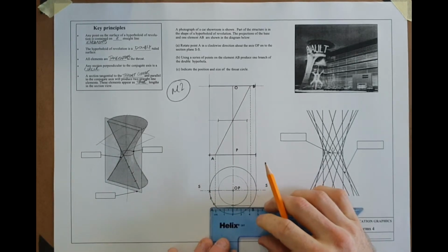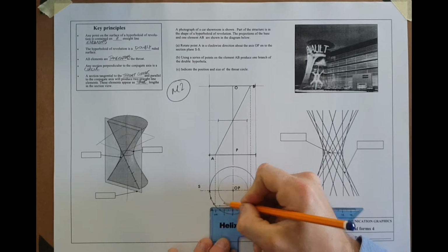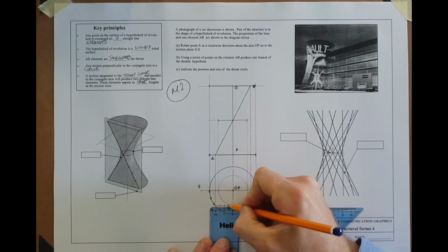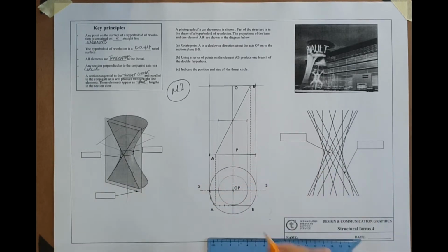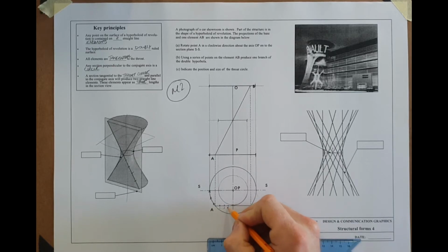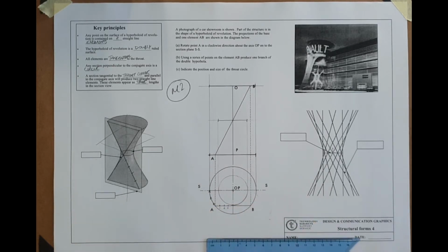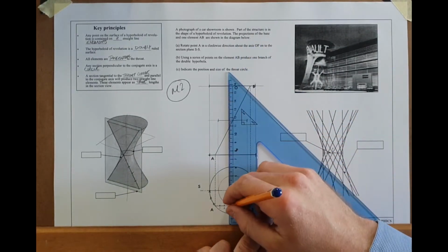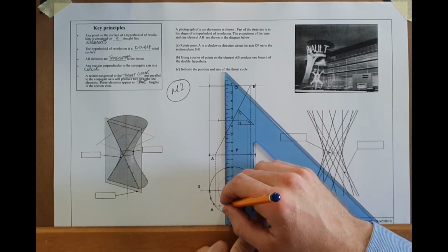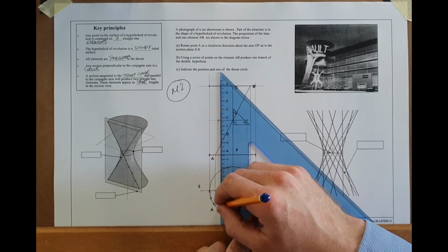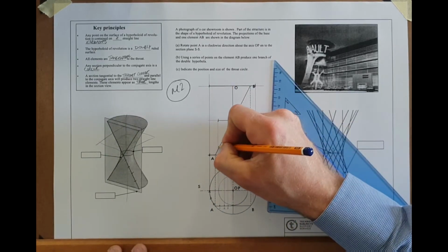So I'm going to lay them down here in plan. In plan it's approximately 20. I'm going to go 5, 10 and 15 there. 3 points will do. Okay, I'll call them points 1, 2 and 3. They are just a point on a line. I'd like to find those same points in the elevation. Point 3, point 2 and point 1.